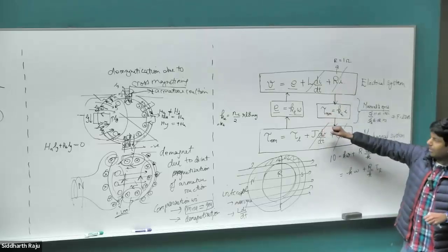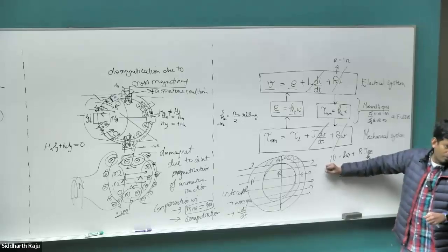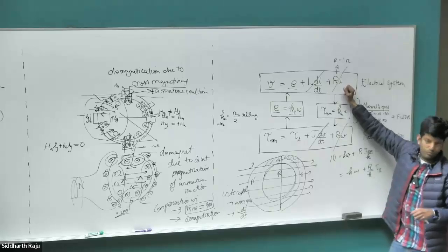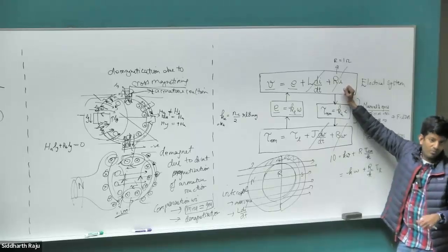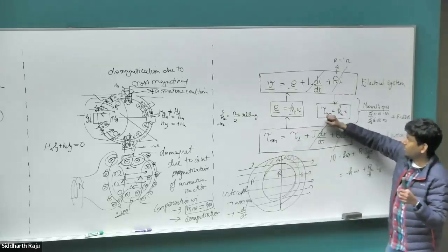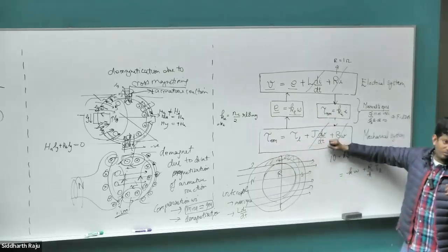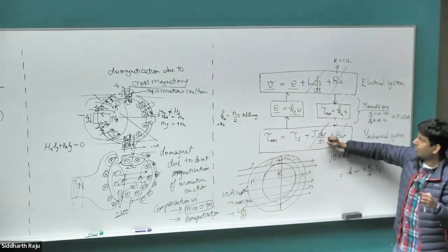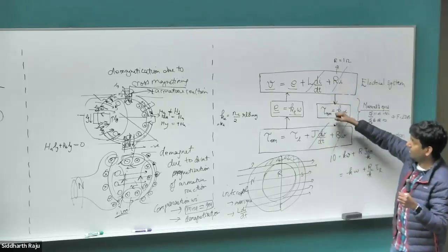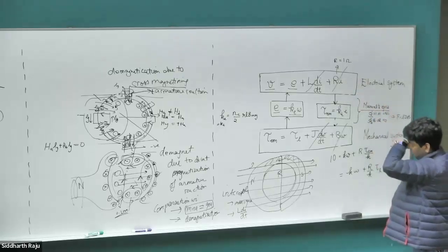So there's just one more value that I need to give if I start introducing other parameters into this equation. If the load torque is 0, then our speed is going to be exactly the same as before. If there is no load torque and there is no friction in the system, there is no need for current to flow in the motor at all at steady state. Because if there is a current flowing in the motor, there's going to be a torque produced. And if there is a torque produced, it is going to infinitely accelerate the system, which will be problematic. So in our case, given that we don't have any friction, if torque is 0, the current is 0.